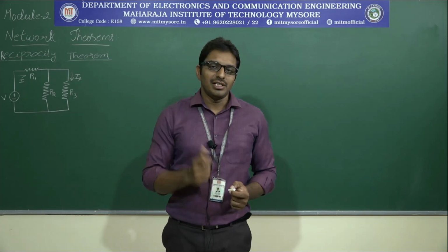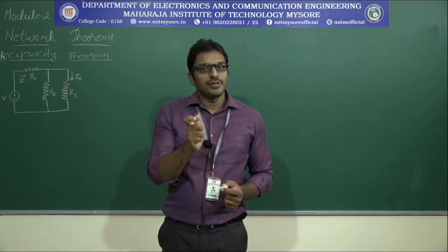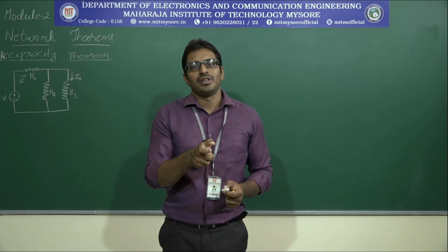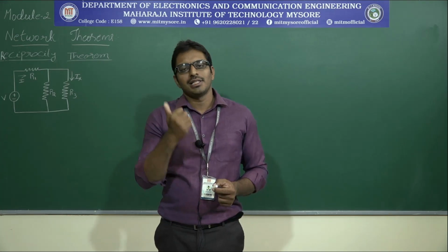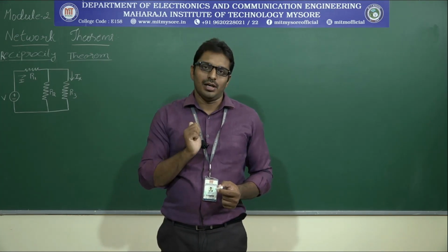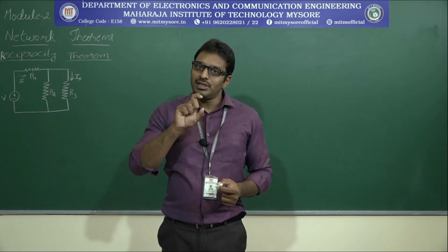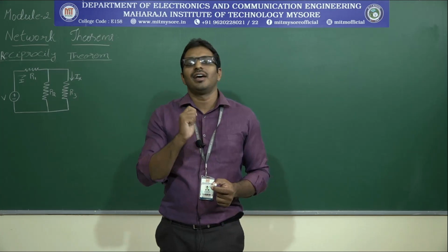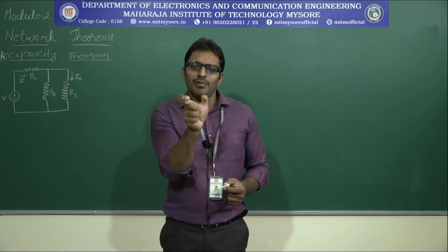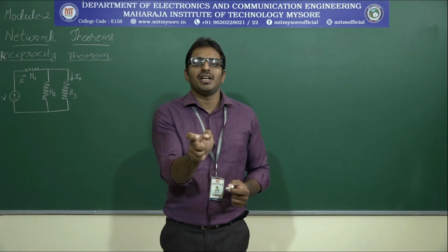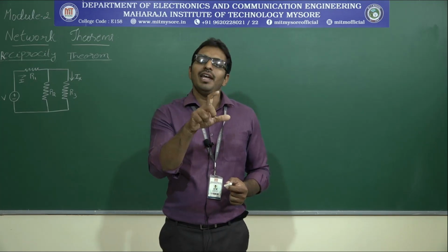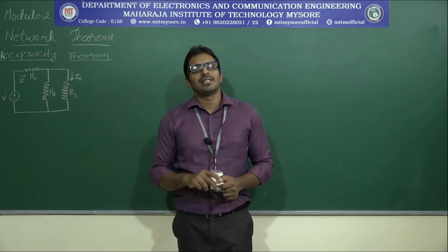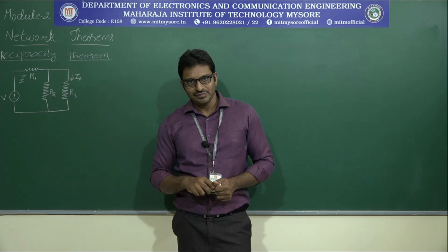For example, if you consider a diode, there is a fixed polarity, anode and cathode. According to polarity only you should connect: anode to cathode is forward bias, cathode to anode is reverse bias. But there is no such polarity for resistors, inductors and capacitors. Even if the polarity of supply changes or reverses, the VI relation remains the same. Such elements are known as bilateral elements.